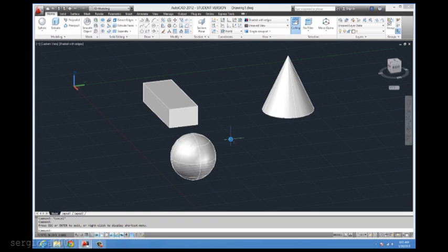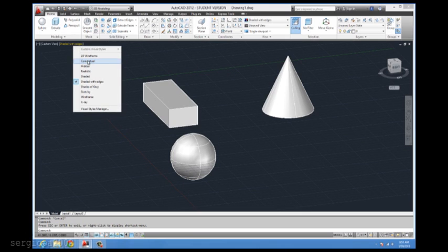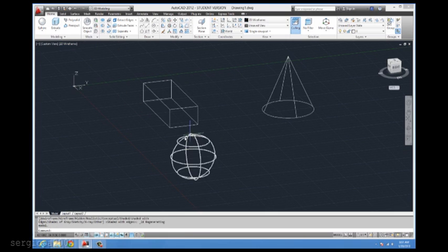So this is how you enter 3D mode and have all the 3D mode options available to you. And also remember to change these visual styles, and it's going to help you a lot when you draw. Especially, the most used visual styles are shaded with edges and also the 2D wireframe, and that will give you the different 3D objects with these wireframes that will help you to just change the shape of these objects if you want. But again, I'm going to talk more about that